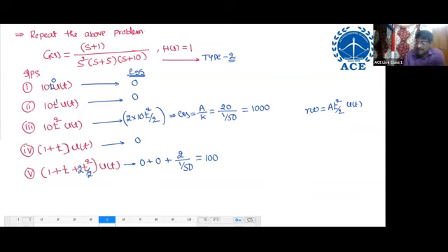Some students wrote correct answers. Very good. So be careful whenever they give the parabolic input. Always adjust parabolic input into the standard form. And another thing, be careful with a type 0 system. Don't take A by K. For step input, you have to take A by 1 plus K. Okay? Next, one more problem.